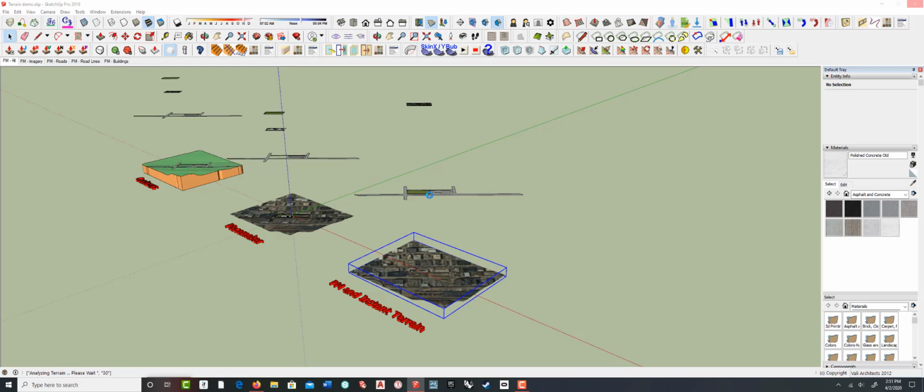And the other thing I'll show you based on this is once we get that down there, we can split the terrain with the roads and the site boundaries like I did before. But we can also, if we want to be able to manipulate the landform across the entire site area, not just on top of these planting beds like I demonstrated a second ago, we really need to be able to map an image of our site plan on there and then use that image as a way to manipulate the landform. And once we've got it regraded, then we can drape the actual geometry down there and split it into pieces so we can apply different materials to it. So that's the process I'm going to demonstrate as soon as my instant terrain appears.